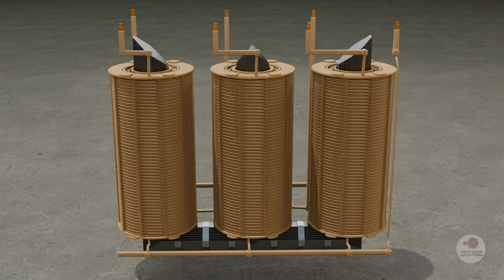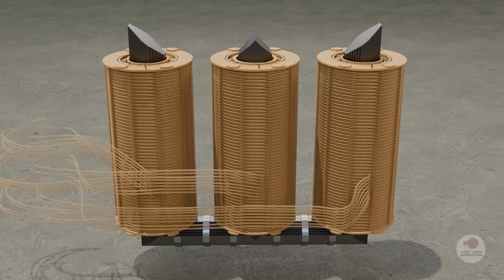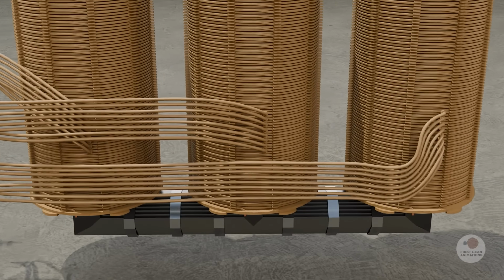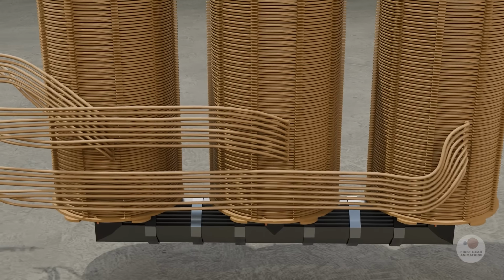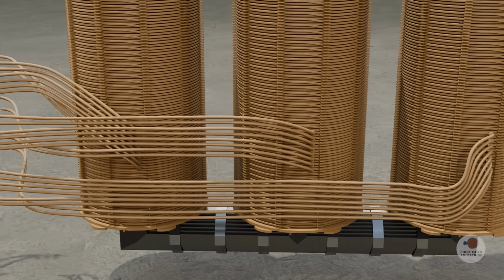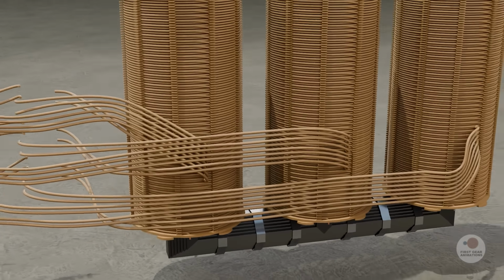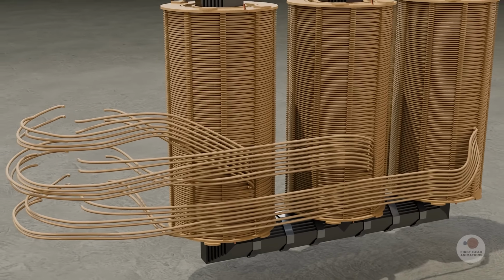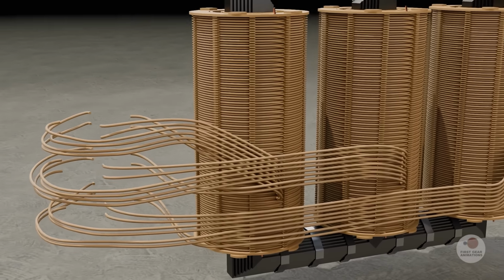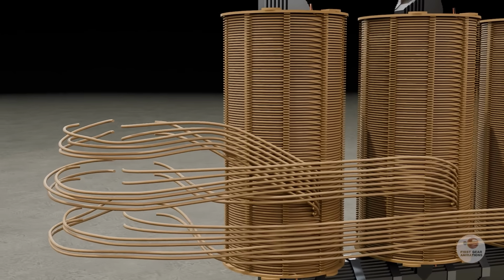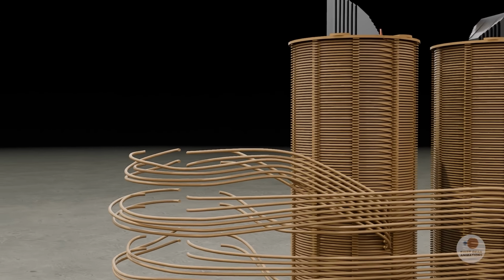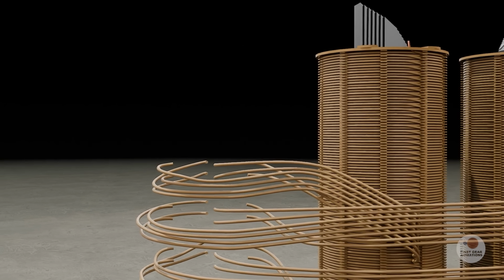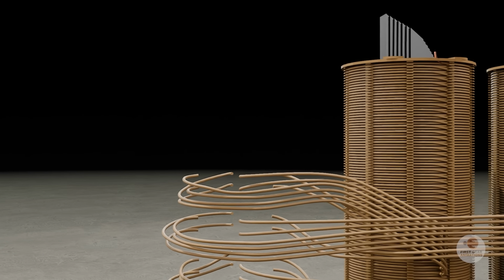Because the grid voltage constantly fluctuates with changing consumer demand, maintaining a stable output voltage is critical. Transformers achieve this using taps. These are specially placed connection points along the winding that allow the transformer's turns ratio to be adjusted. Taps are almost exclusively placed on the high voltage windings. By positioning the taps on the high voltage windings, we leverage their outer position for easier accessibility and their higher number of turns for pinpoint precision. Since the current level on the high voltage side is also lower, it minimizes the risk of electrical arcing on the contacts during a switch.